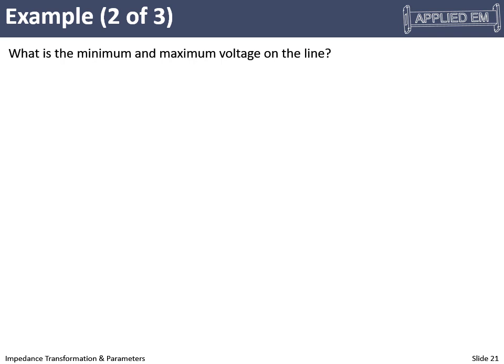Next question, what is the minimum and maximum voltage on the line? We know this won't necessarily be exactly our driving voltage because we have a standing wave that can make that bigger and smaller than our driving voltage.